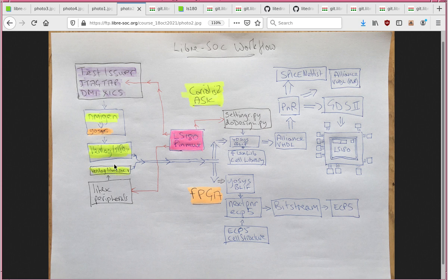And then we went over that Migen contributes to it. Ultimately the ls180.v is compiled to Verilog, and LiteX's peripheral system generates the fabric where the LibreSOC ls180 is a component connected to that fabric.